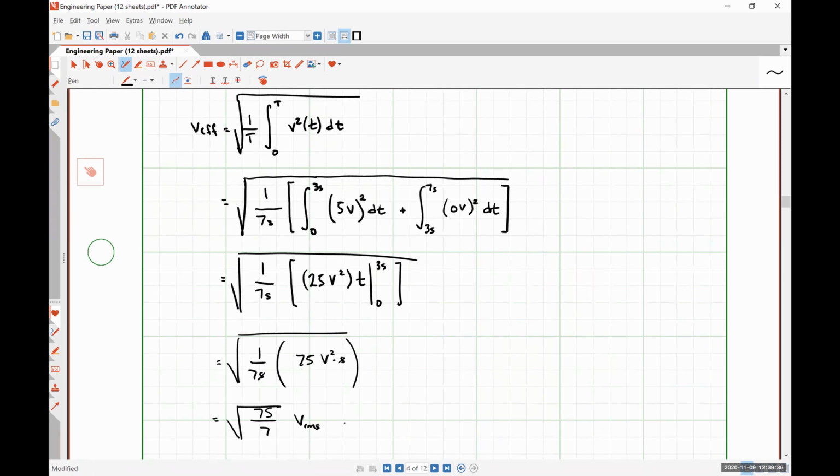This lets us know that we are dealing with the effective value of the waveform versus the instantaneous value of the waveform. So if you ever see something with the units of volts RMS, it means you're using the effective value. So when we talk about the voltage coming out of one of the receptacles around the room, that is not 120 volts DC, nor is it a 120 volt AC amplitude. It is 120 volts RMS, because that is the effective value of the voltage that's being provided by that socket.